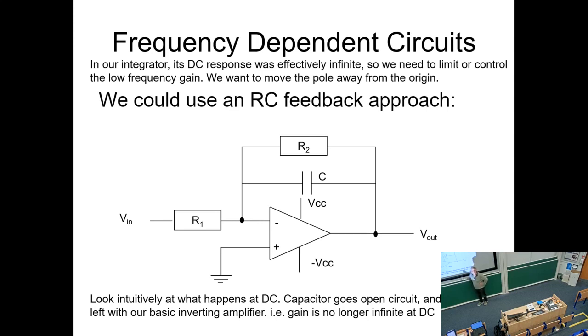Okay. Now, what happens at high frequencies? The capacitor becomes a short circuit. Any current going around here will go, I want to go down the easy route, not the hard route. Yeah? So effectively that resistor's not there anymore because this is a very low impedance path. So we're back to what we had before, which means we get zero or very low response in terms of output at high frequencies.